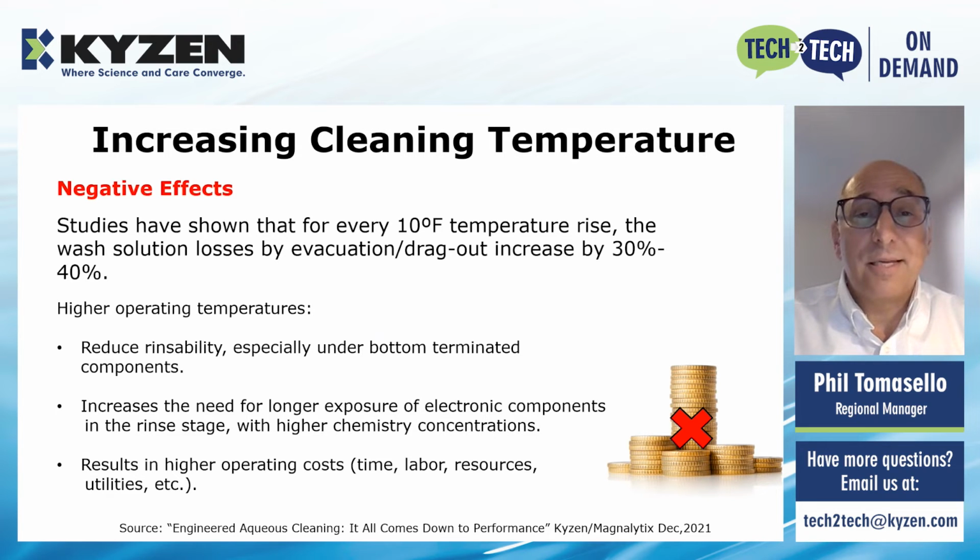The higher operating temps you see, they're certainly at some point going to reduce rinsability, certainly under the bottom terminated components. It's going to increase the need for longer exposure of your components in the rinse stage with higher chemistry concentrations. Candidly, this will result in higher operating costs of time, labor, resources, utilities.